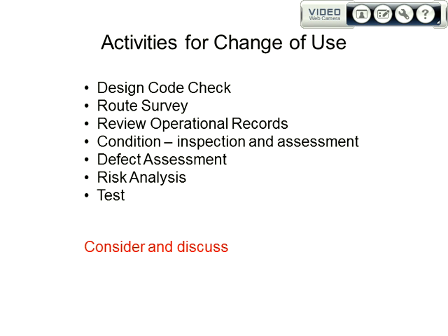Now, what do you think? Do you think a CO2 release is going to be hazardous? Right, okay. And why is it going to be hazardous? Exactly. So the criteria for assessing risk that are used for a gas pipeline, which is a thermal hazard, they're not going to apply. So you need to draw these things out. Okay.